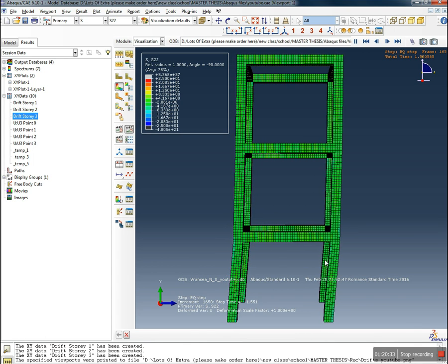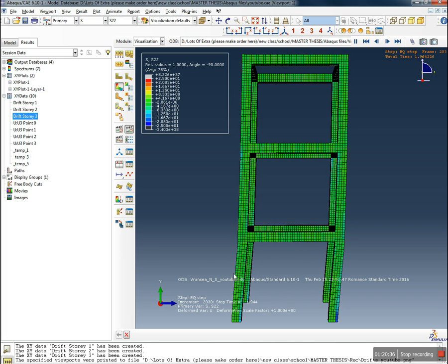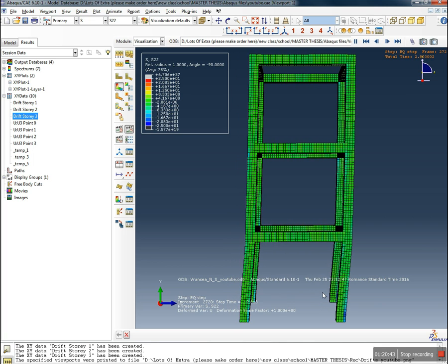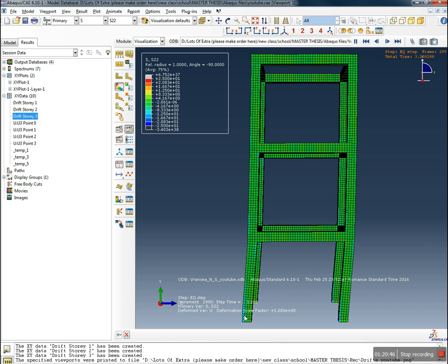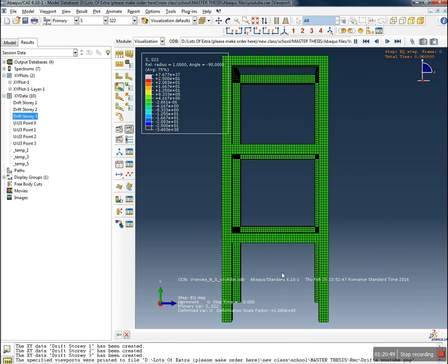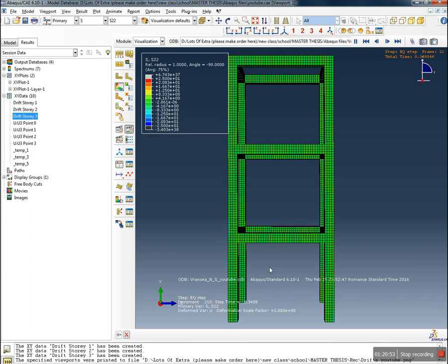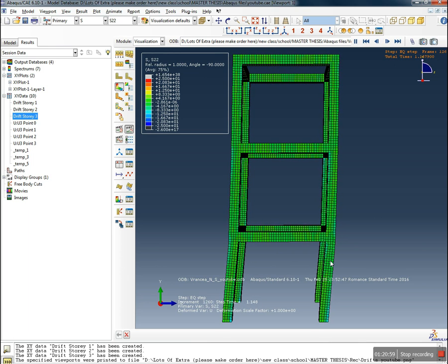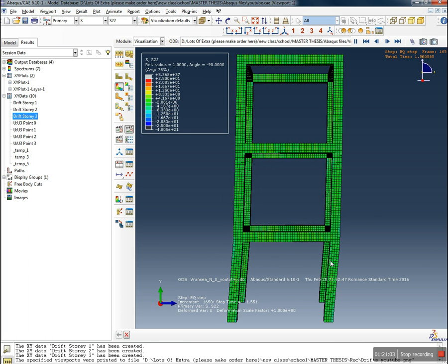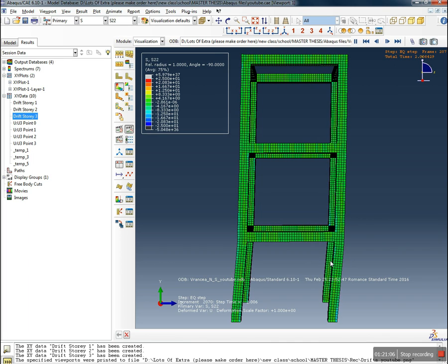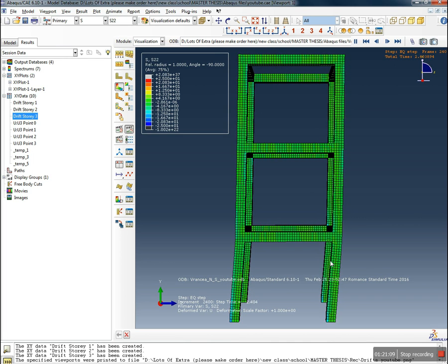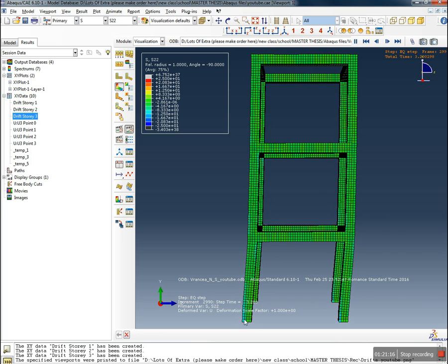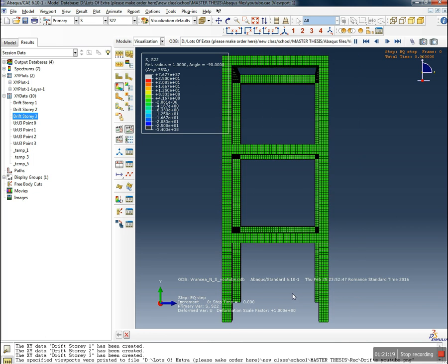Yes, and that's what I mentioned the solutions for: increasing the height of the story for extra flexibility, and also placing the stirrups much closer to each other. Of course, this model has no stirrups. They are not that difficult to define and model. They are just some wires, and then you just describe them as square. So just some square wires with some specific cross-section and material properties. That's basically what the stirrups are and how you could define them, and then you can just create one stirrup and create a linear pattern, and you just place them where you want. So that's how it goes with the stirrups.